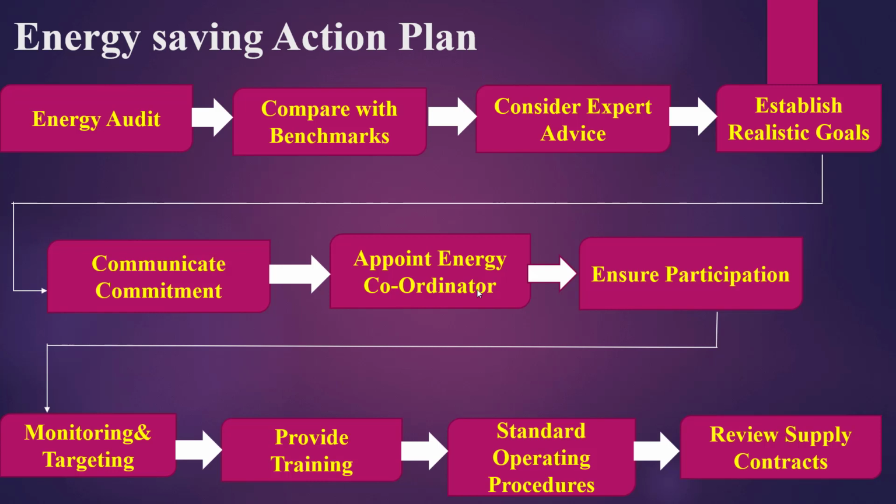Monitoring and targeting systems. In its simplest form, monitoring and targeting can be performed manually. This involves reading meters regularly, establishing consumption targets, comparing actual consumption against targets, and taking corrective action where necessary. Computer-based M&T systems can read meters and sub-meters automatically, including those at remote sites, undertake various statistical analyses of the readings, and produce regular management reports.